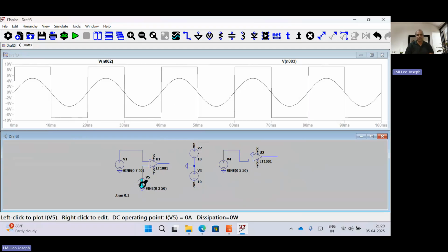Like that. So here also you can do the same process and estimate how a non-inverting comparator is going to work. Okay, so now instead of starting from plus V saturation when it is positive, it will start at minus V saturation. If I switch this point from plus to minus, minus will have the majority first.